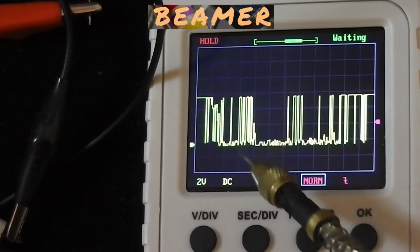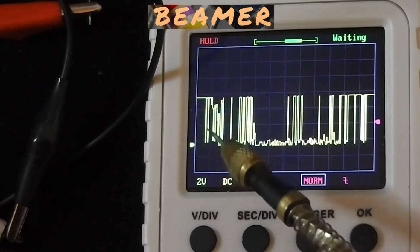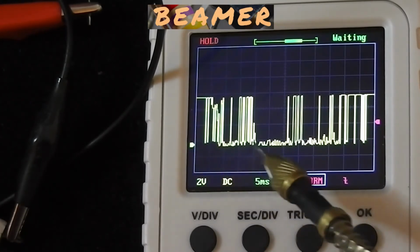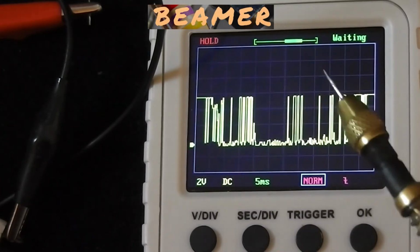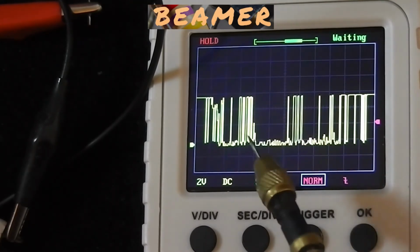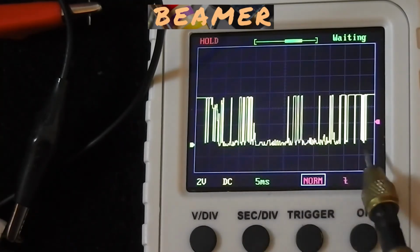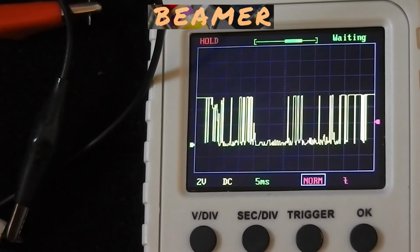And as you can imagine, if that's driving an inductive load, there are going to be consequences for this kind of waveform. We tend to think of a switch as operating in either on or off, but in reality this can be squirting out quite a high frequency here, and intermittent on and offs.